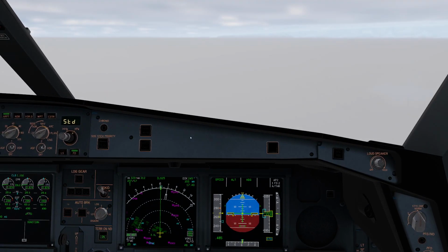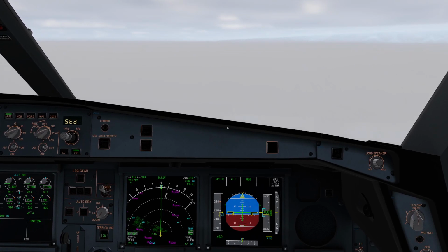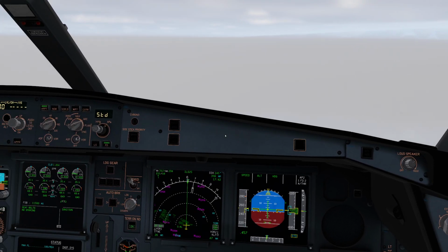Alright, and that is the cabin pressure and emergency descent exercise already completed. As you can see, applying those memory items isn't that difficult, but it does need some discipline, and in the situation in which you get when the decompression happens, it certainly isn't that easy, even though it may look like it from a classroom exercise as we are doing it right now. Especially when you're sitting there with a mask on, then the mask may be fogging up, so that's also something to keep in mind. And overall, that is quite a bit of work.